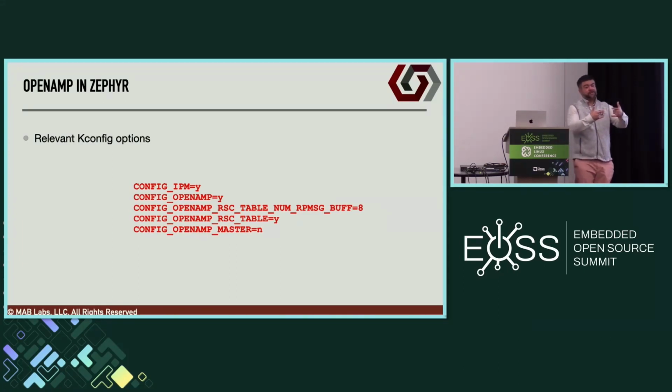So that's one of the first things remoteproc does, and we'll see how that loading process works, which is very straightforward. There's a kernel module on the Linux side that checks and parses the ELF file to make sure that it meets certain requirements. If it doesn't, it throws errors, but if it does, it starts the process of loading that into the MCU. One of the things it checks is that this resource table entry is present in your ELF file.